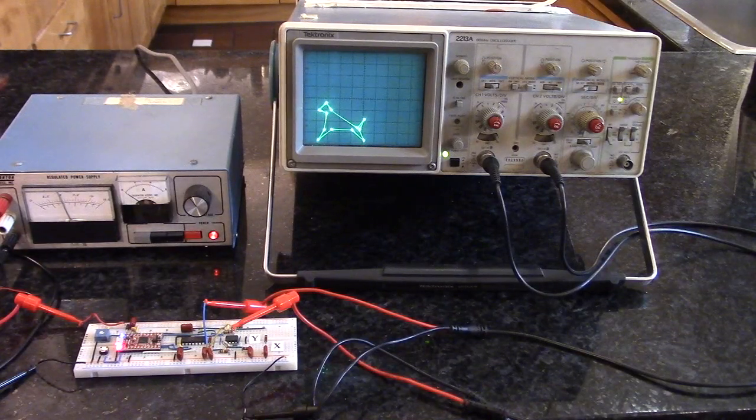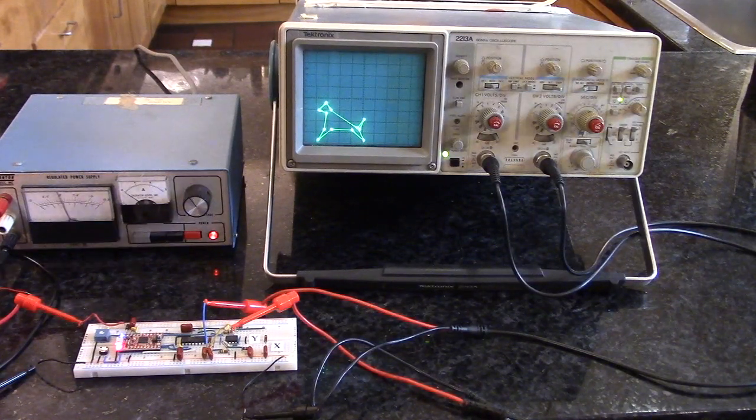The DAC that we would be using is an 8-pin device. It has an internal reference of 2.048 volts, so that's the largest output we can get. It comes in 8, 10, or 12-bit versions. They're all identical, and they did something smart, which is you send a 16-bit value through the SPI, and the lower 4 bits are used for the 12-bit version. We ignore the lowest 2 bits for the 10-bit version, and we ignore the lowest 4 bits for the 8-bit version. And what that means is it doesn't really make a difference which version we use.